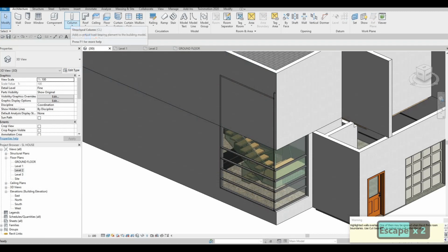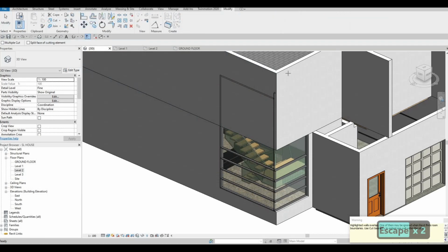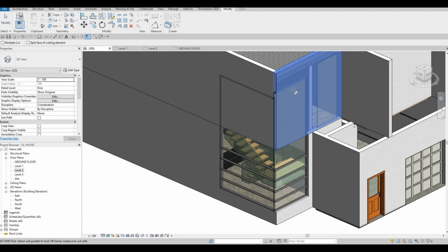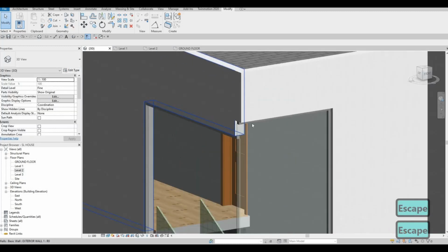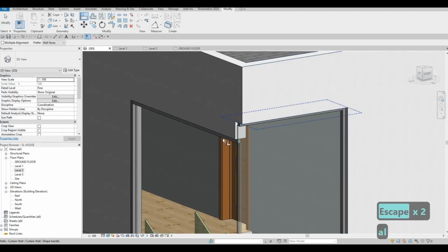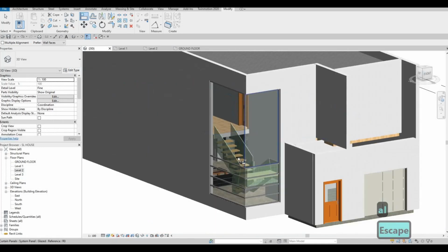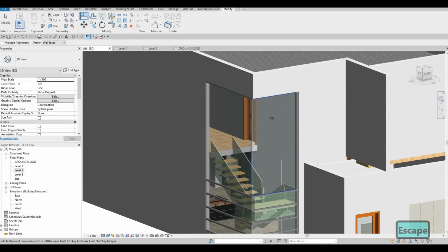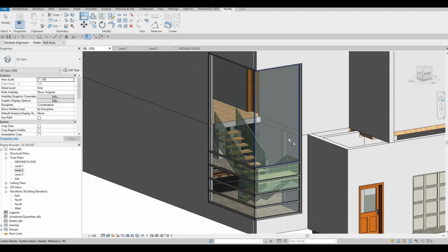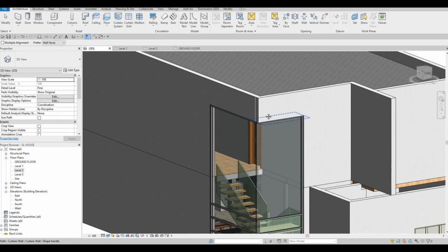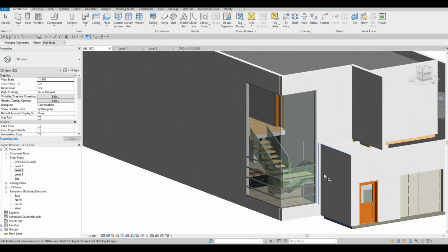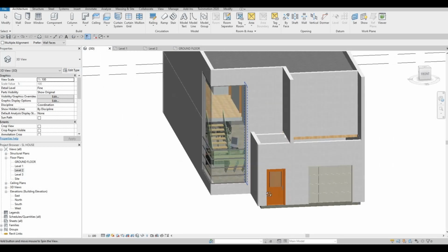And then we could just cut geometry right now. Select the wall, and then the curtain wall can be selected as well. Wall and then curtain wall. There we go. And then now we could just align them so that they have the same height. And then we're going to put the same curtain grid lines here, and then it will look the same for that.